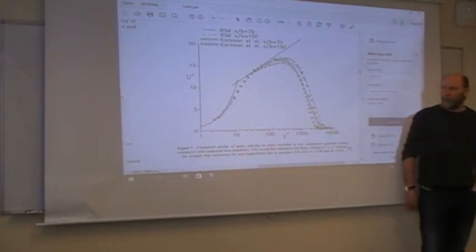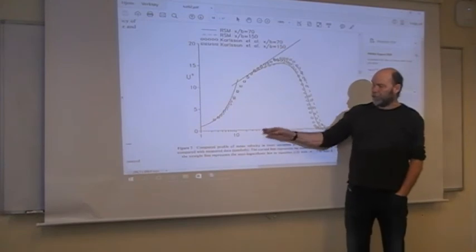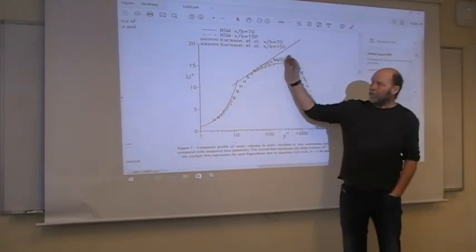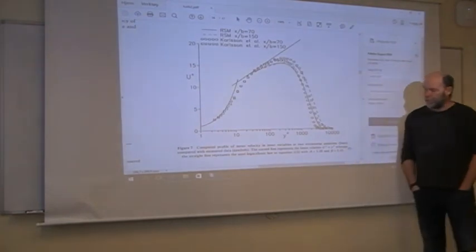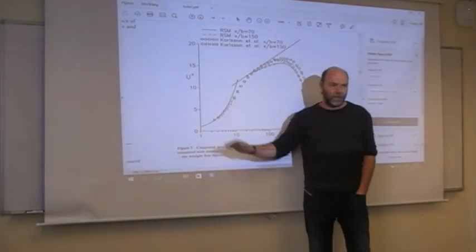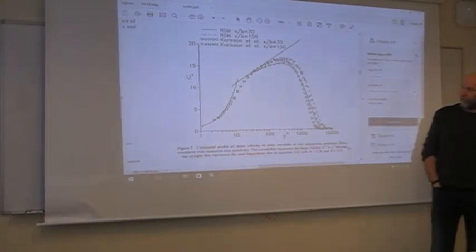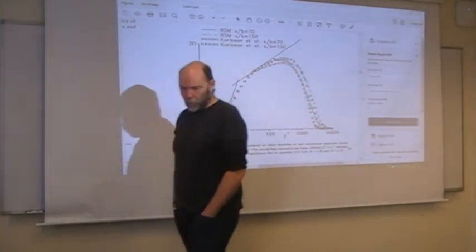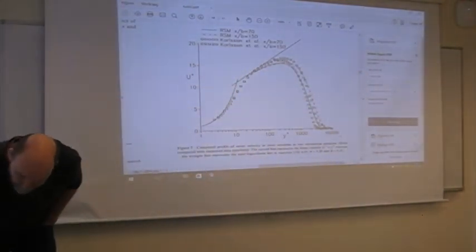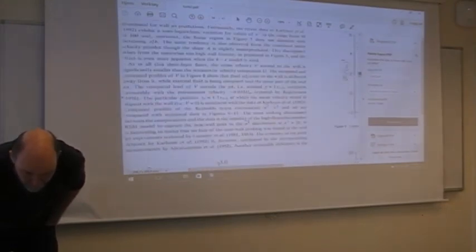Then you have to use a high Reynolds number wall model, so that you can put your first grid point in the log layer outside the boundary layer. Then the wall model has to take the behavior into account with models, or else you will get very, very strange results. So wall models are a fairly important part of any turbulence model.